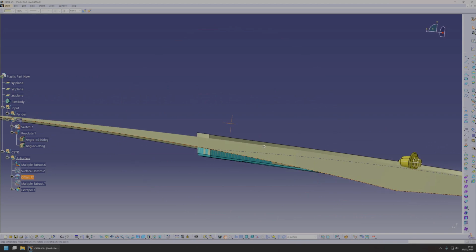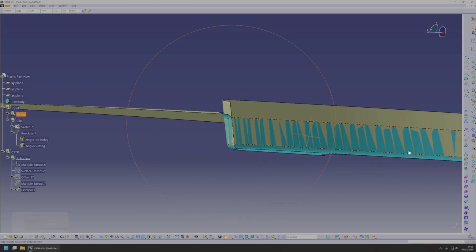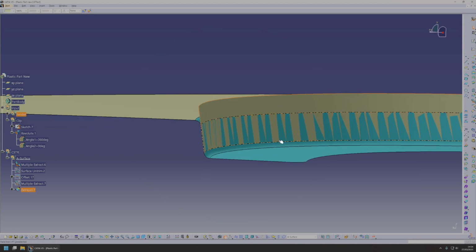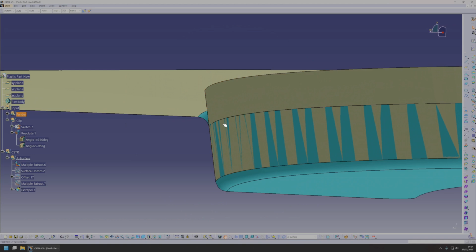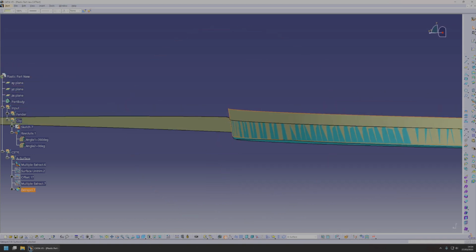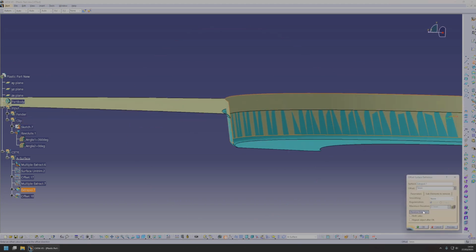Now we can go ahead and hide this upper surface, because we want it to have a slight curvature here, that it goes like a chamfer on this. It'll go up and then to the level we wanted it. And it also needs to have a gap to this. So the surface we just extrapolated, we will offset by a set amount.